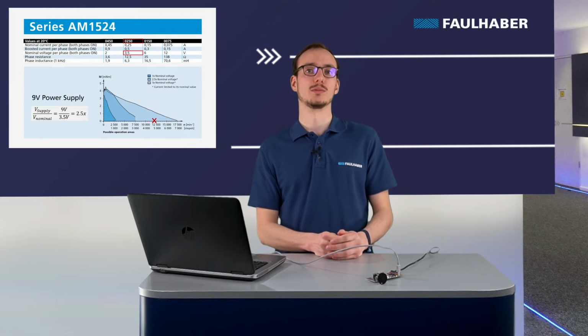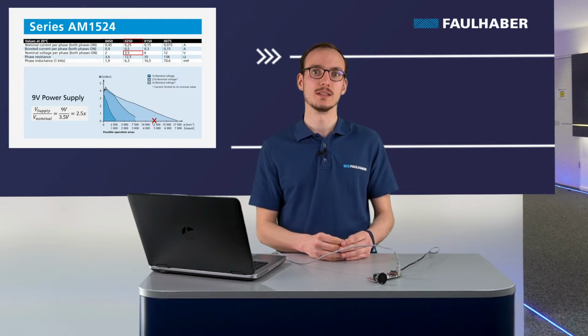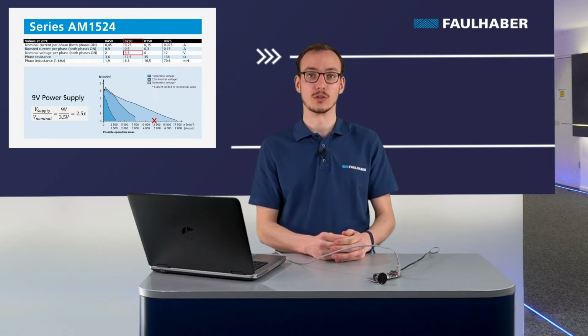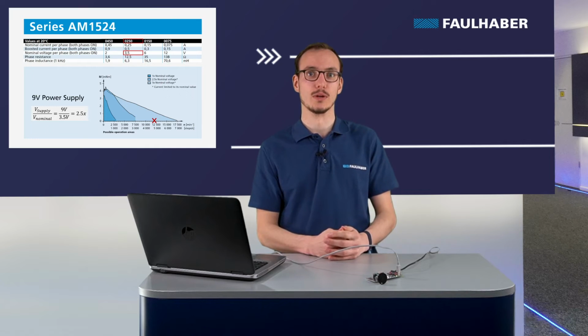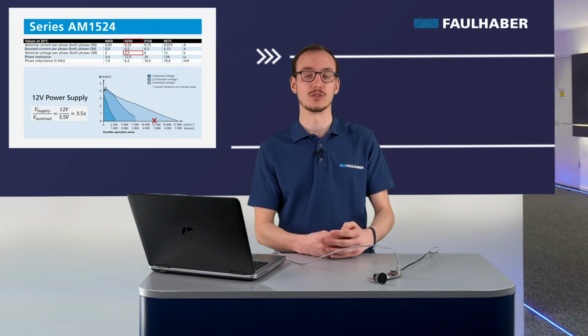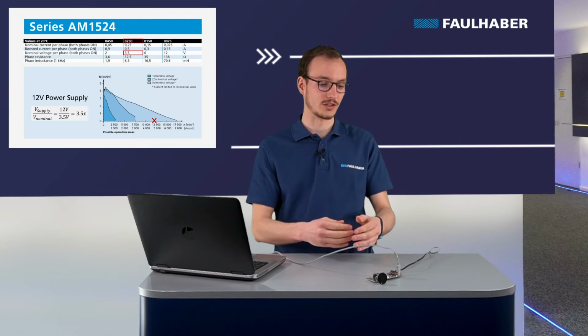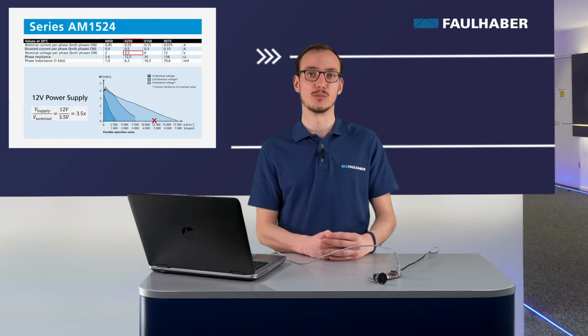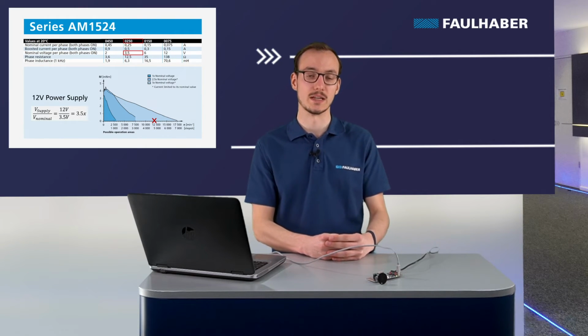As we've seen, the stepper motor stalled and stopped abruptly and had a high pitching noise. This is because the motor was unable to reach the target command of 12,000 RPM. Now we'll proceed the same, but with a higher supply voltage. So now I've changed the voltage supply to 12 volts, and again I will give the command to the stepper motor to reach 12,000 RPM.